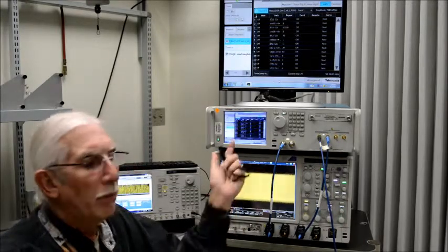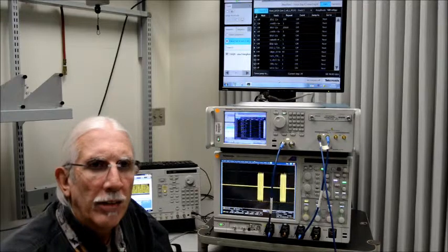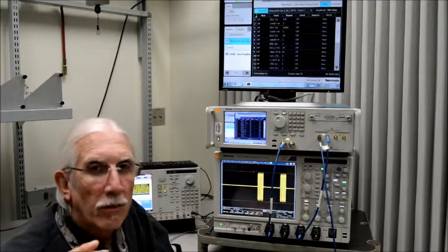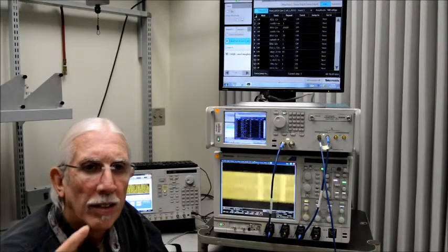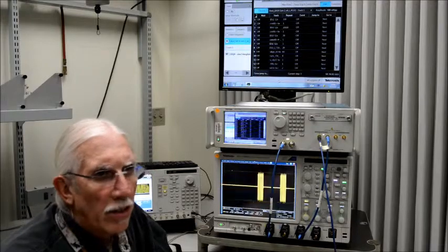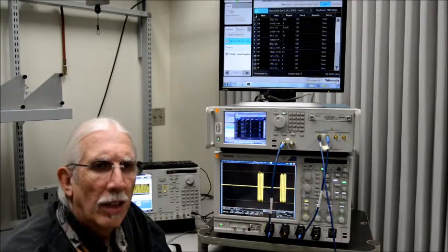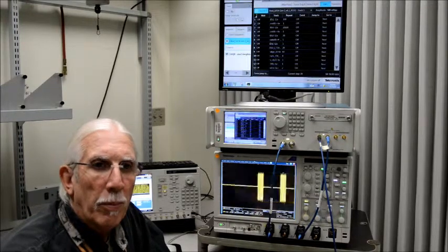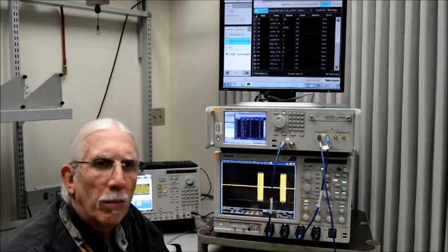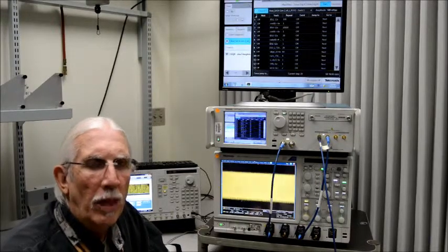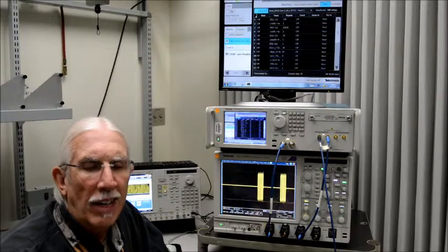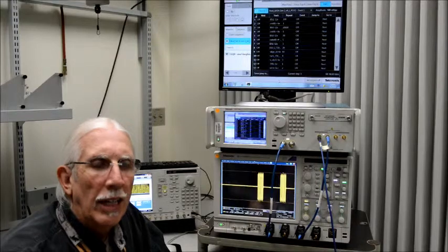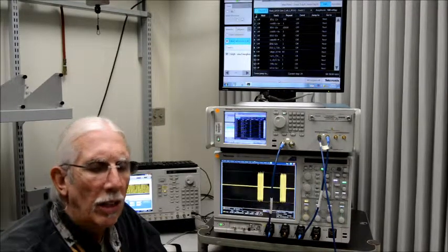Here I've loaded a little bit more complex waveforms. In this case, it's a serial data application where the first part of the sequence is used for putting the DUT or the device into a loopback mode, and then actually running waveforms that have the jitter content provided so that you can make sure that the device works in compliance conditions, where you have to add a certain amount of jitter, a certain amount of ISI, a certain amount of random jitter, and then combine it all into the waveforms and test it and make sure you don't get any bit error rates.